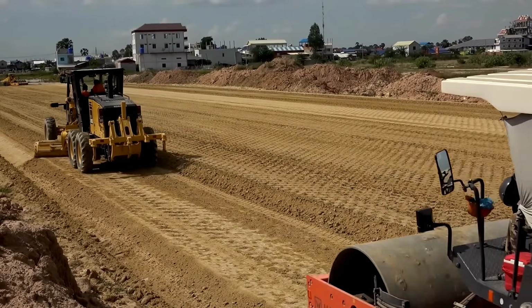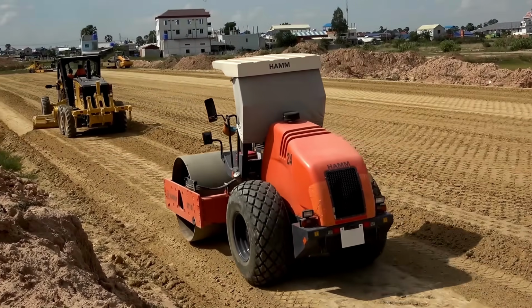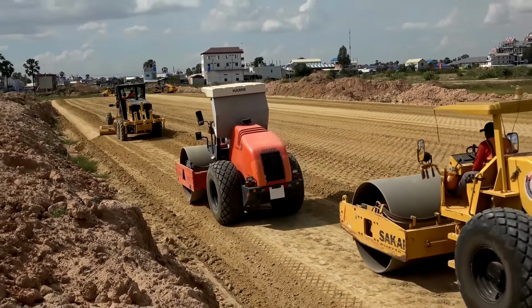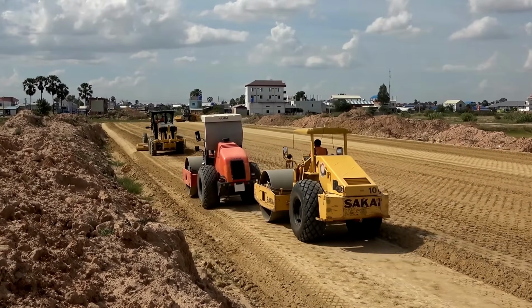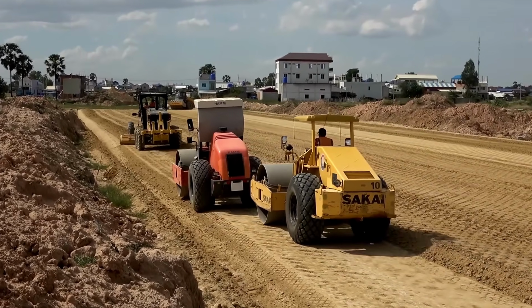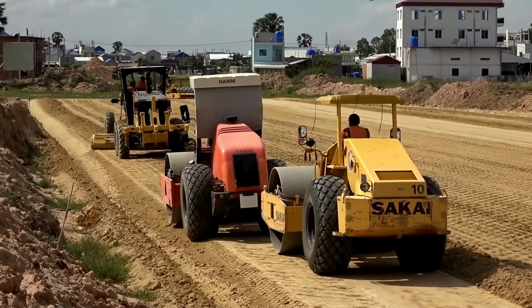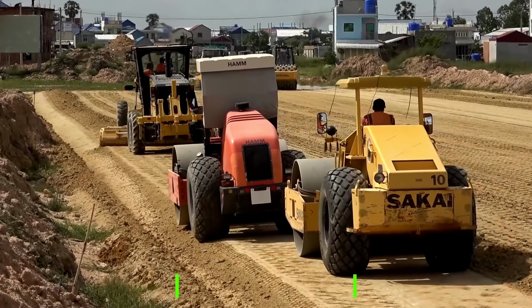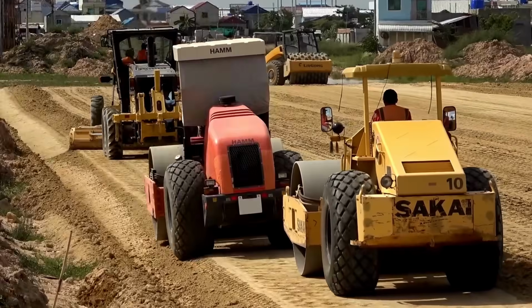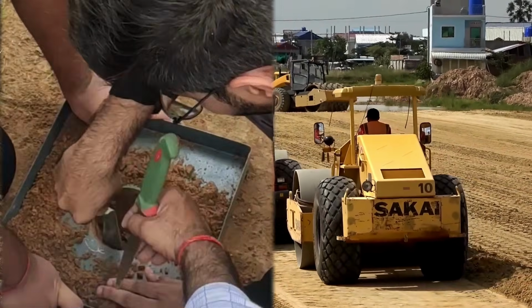Compaction shall be carried out mechanically using vibratory rollers of 80 to 100 kilonewtons static weight, covering the entire width of the pavement. Rolling shall commence from the lower edge and proceed towards the upper side with 1/3 overlap. Generally, 6 to 8 passes are required to achieve about 98% of laboratory density. Each layer shall be tested using the sand replacement method.